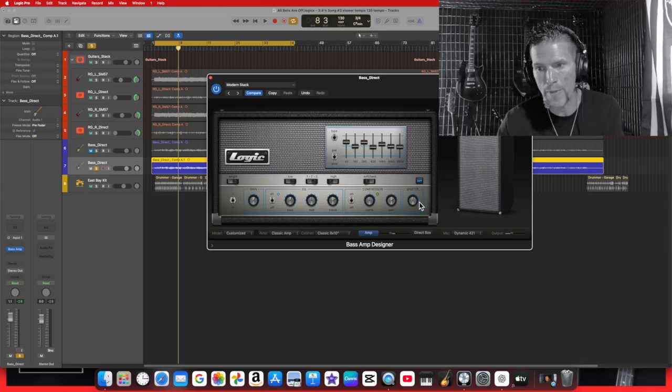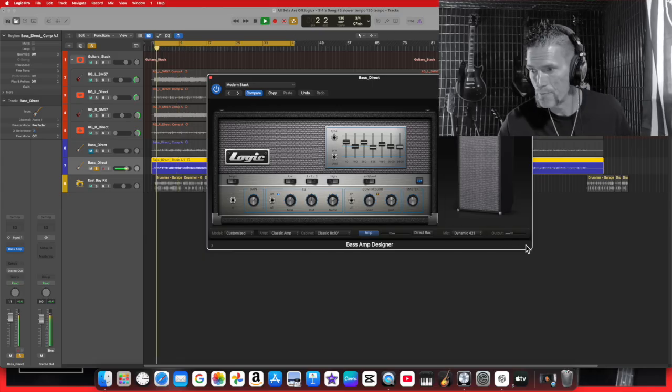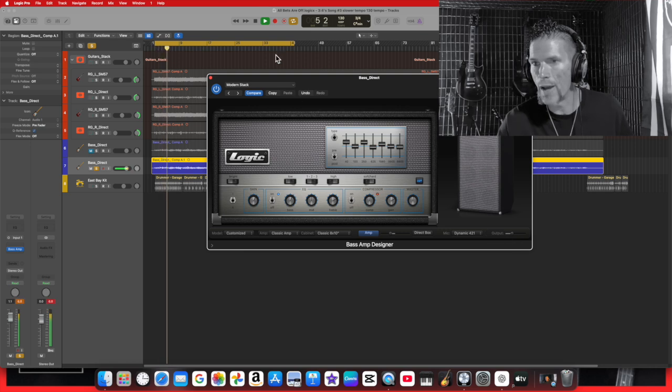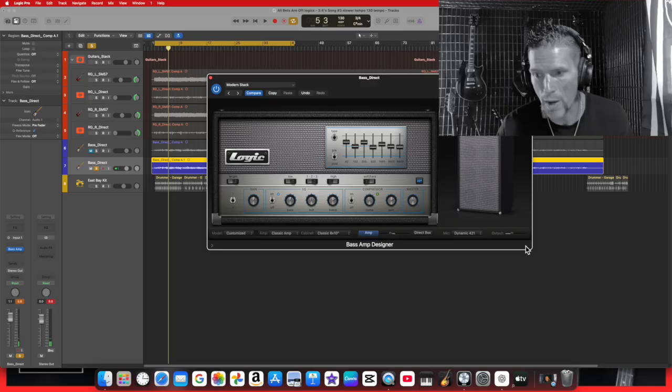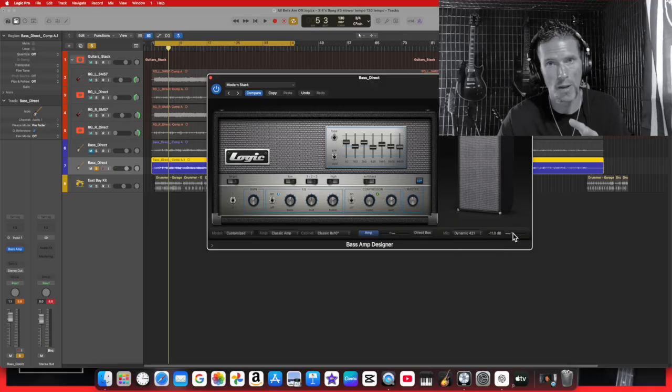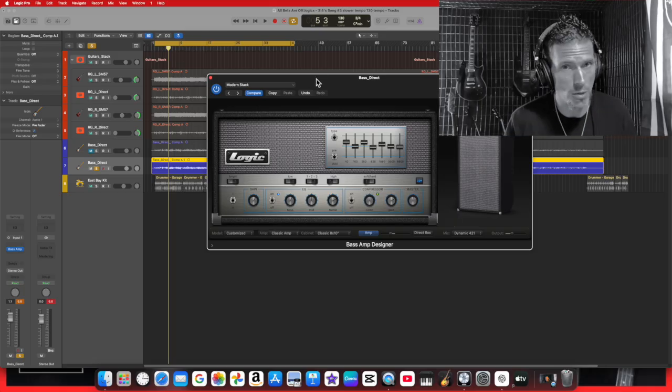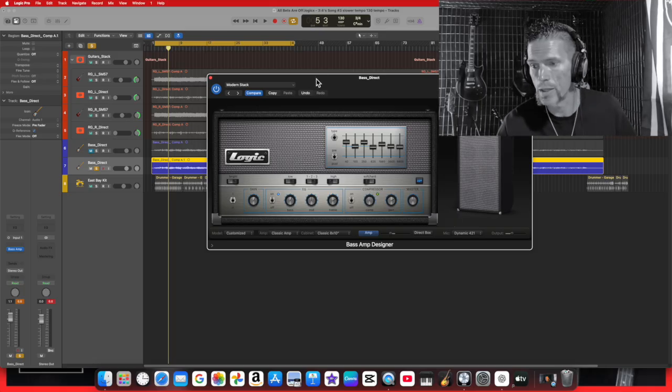and just turning up the master or the gain's not always going to make that better. So over here at output, you can always turn up your signal a little bit there if it's too quiet, okay? So you don't want it too high, because it will start clipping. But that will help you out if your signal's too quiet. It's best to turn that up a little bit. But use a level meter or a VU meter to do that with, okay? So it doesn't start naturally distorting and clipping your signal and stuff like that, okay?